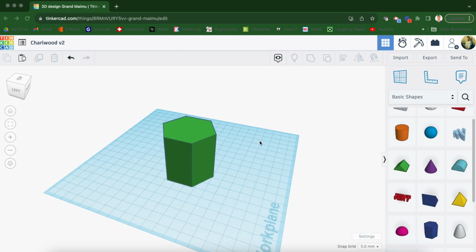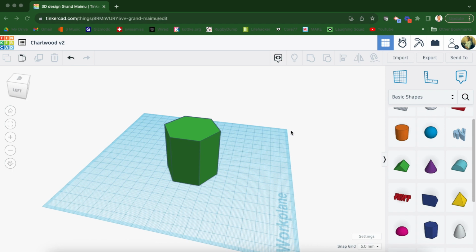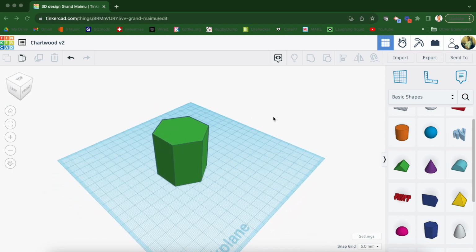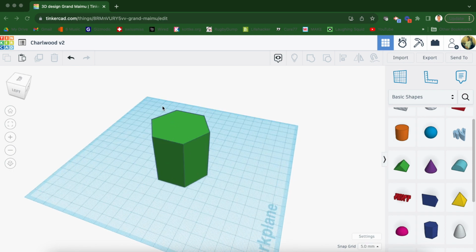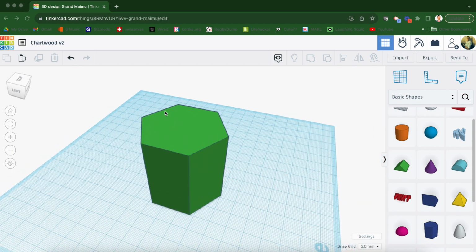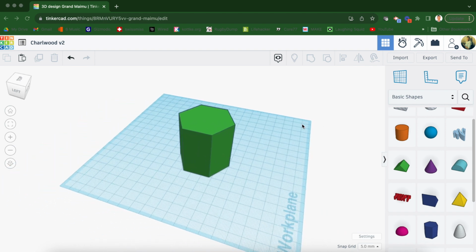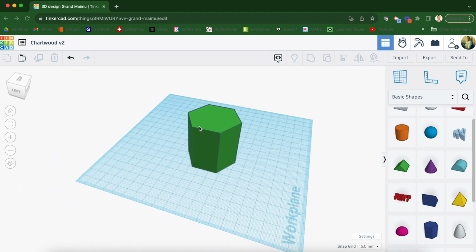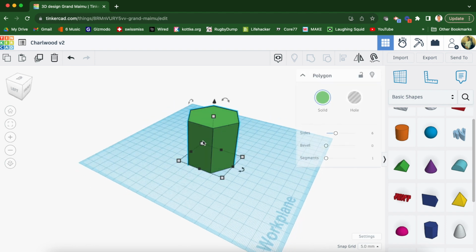There are a few mouse controls you'll need to use and master to navigate this 3D space effectively. Right-clicking and holding and moving your mouse will orbit around. The mouse scroll wheel will zoom in and out of the area that your cursor is in. Holding and pressing the middle button whilst moving the mouse will pan from side to side. Left click allows you to select and unselect objects. You can also nudge shapes using the cursors on your keyboard.